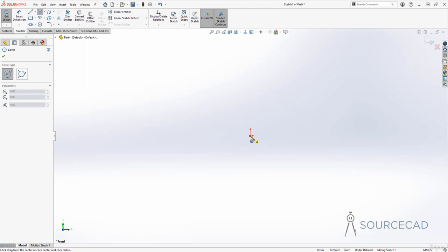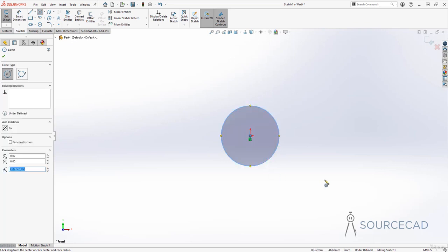So I'll use this origin, and using this as a center I'll just make the circle. That's it. You need only these 2 points. Now we have a circle of approximately 32 unit here. You can specify the radius value right now, right here if you want to. For example, I'll type 30 and press enter, and this will change. Or you can also specify this radius value later using the dimension tool. So in this case I'll leave the circle and I'll press escape.